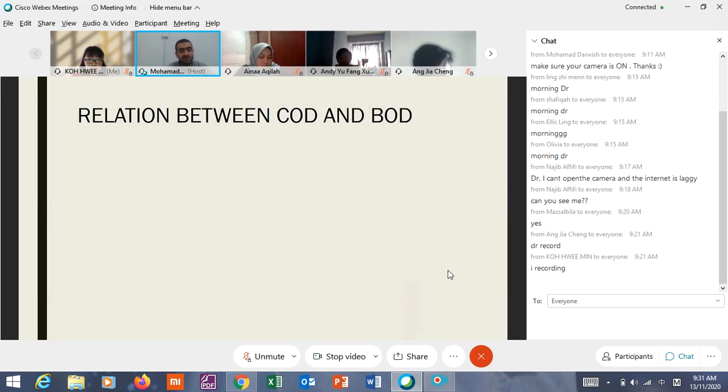Now, this is one of the important things we have to understand: the relationship between COD and BOD. As we said, COD measures the concentration of all organic matter, biodegradable and non-biodegradable. But BOD measures only the biodegradable.